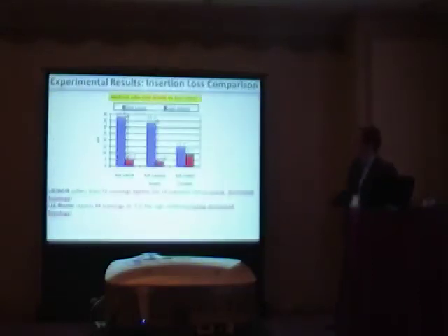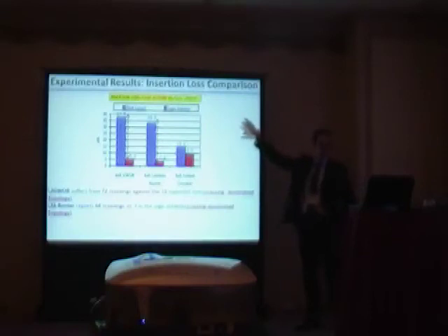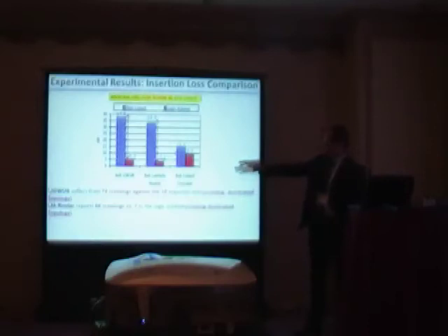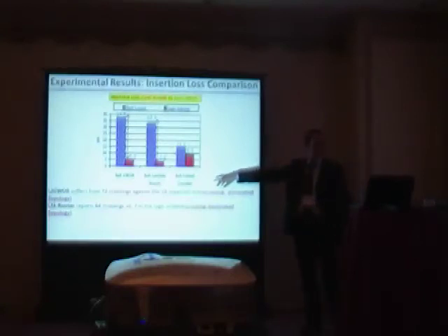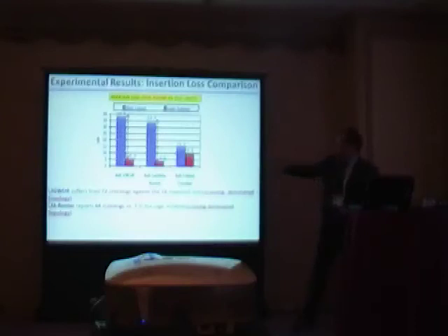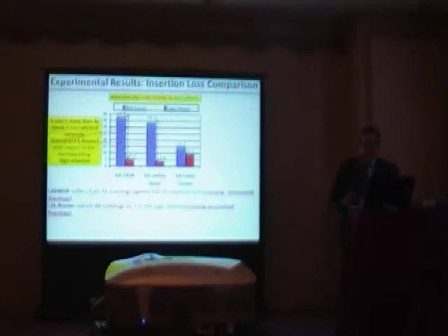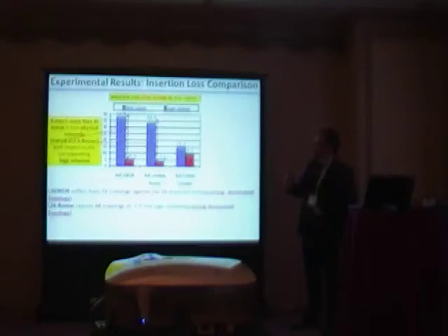As you can see here, we compare the insertion loss across all topologies analyzed so far, contrasting the logic scheme and its physical implementation. Notice that the G-board counts 72 crossings in the real layout, instead of 10 crossings in the logic scheme. In a similar fashion, the lambda router reports 74 crossings in the real layout and 7 in the logic scheme. Both topologies are crossing dominated. In fact, IL max is more than 6 times higher with respect to the corresponding logic scheme.